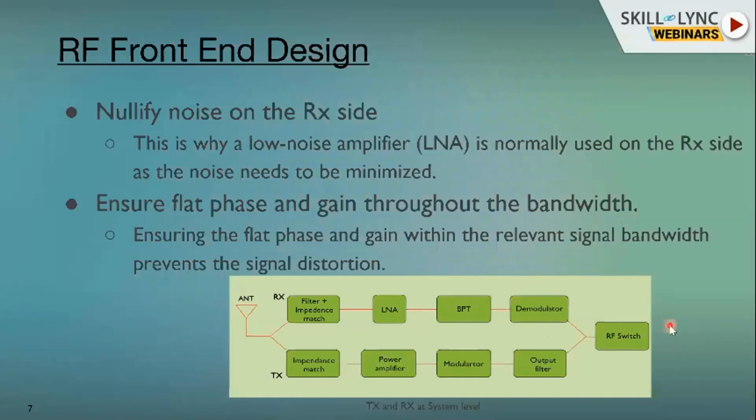The basic difference was that the noise got mixed with the receiver side signal and amplified by the low noise amplifier, and it went to the A to D converter, and along with your voice or whatever signal you were supposed to receive, you were actually receiving the noise.